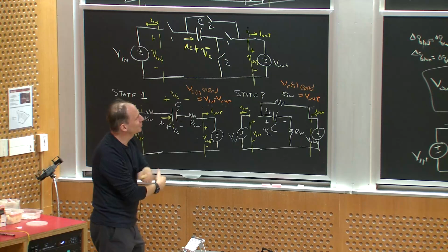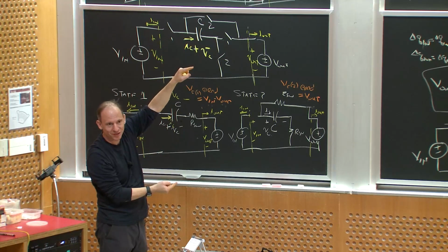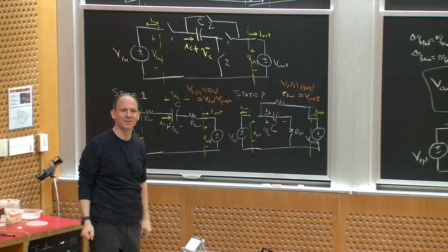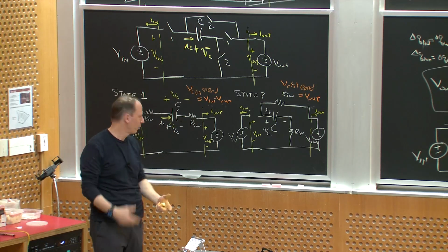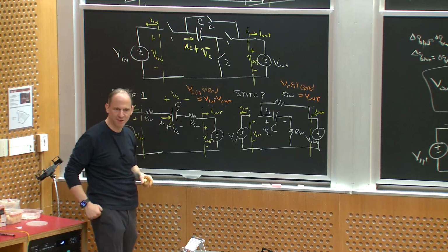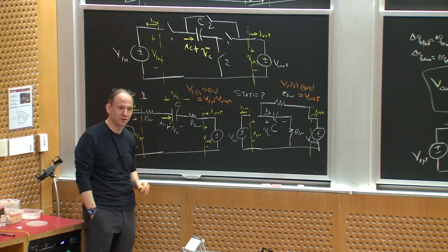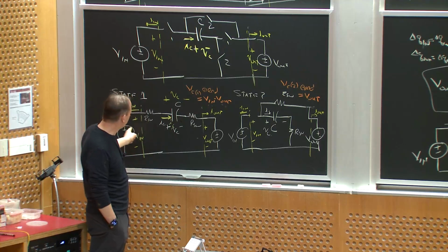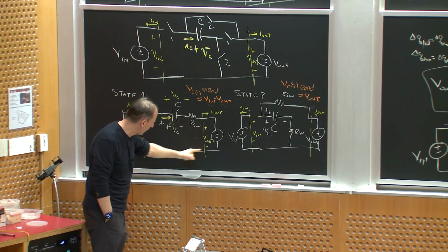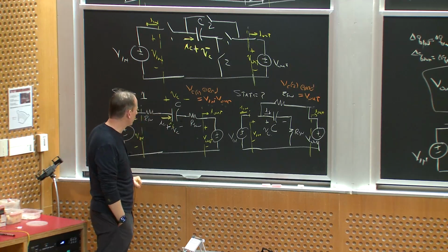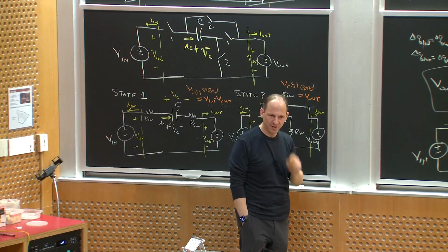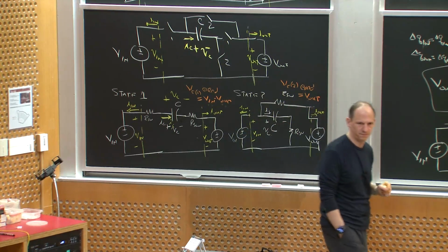Well, all that happens is that the peak charging current gets higher, and it goes for a shorter time, and the total loss is the same thing. Okay, so mathematically it works out. The actual value of the resistance doesn't matter. It doesn't even matter if the resistance is linear or nonlinear, but you get the same net loss. So it's basically the loss that I incur in putting the charge on the capacitor and then taking the charge back off the capacitor to the output. That's the loss that's included.